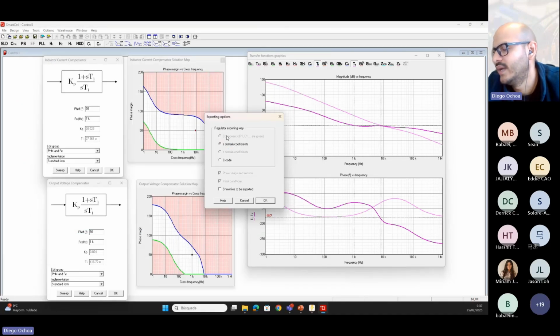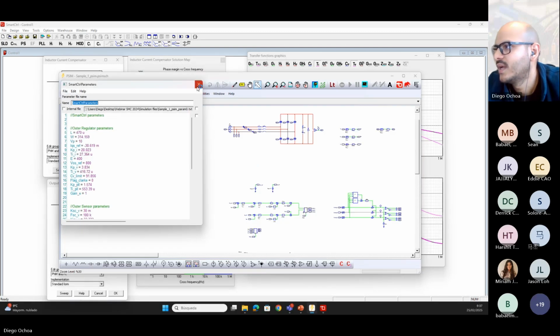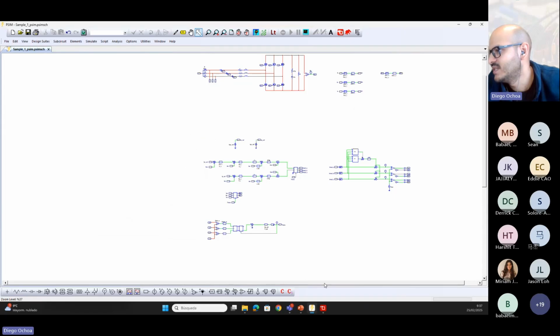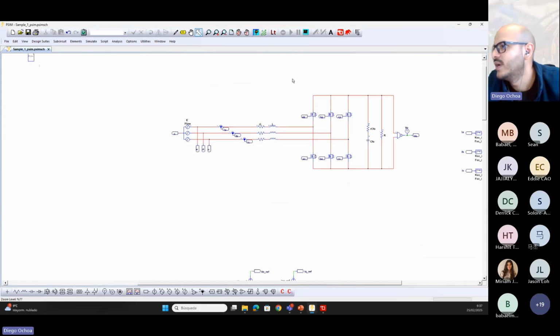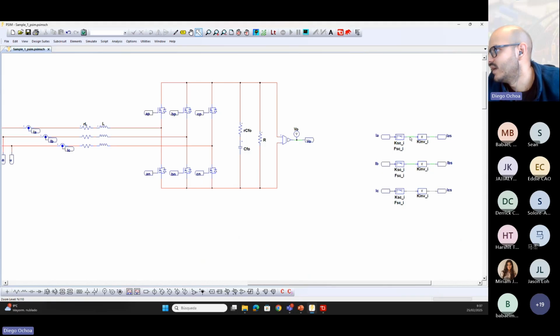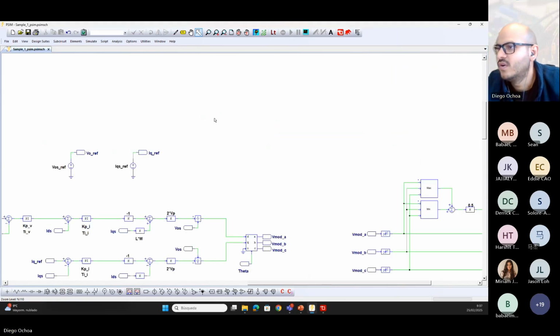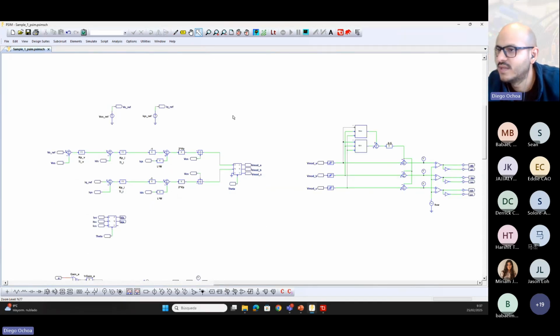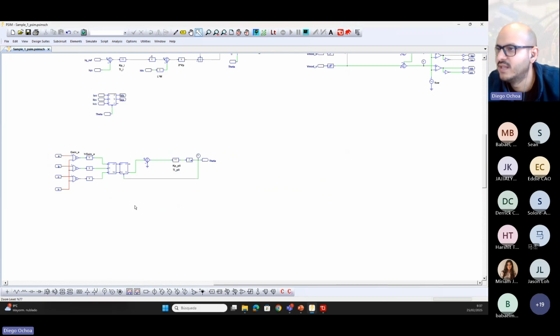You can use the PSIM functional elements. This is the version I want to show you. Click on OK, and now you can see that SmartCtrl creates a PSIM template for you. Here we have the power stage, and the sensor stage with the transfer functions. Also, we have the control structure that I showed you before, and this is the modulator. And here we have the PLL.